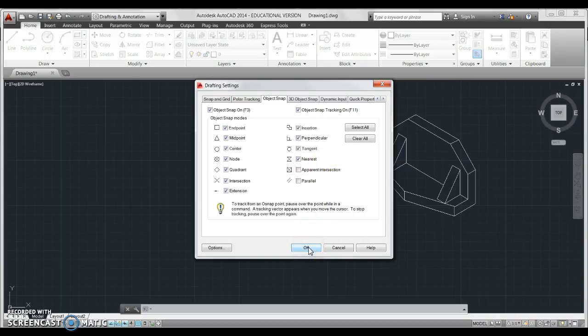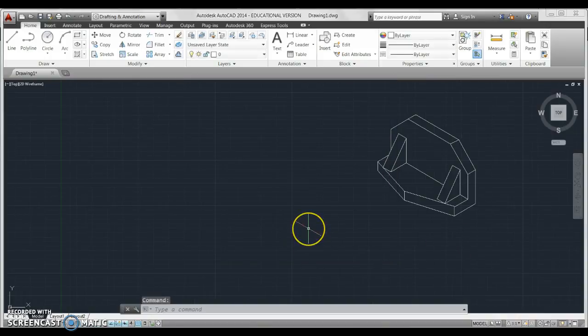And you're going to notice that right now the grid is little squares. When we click OK, it's going to switch to isometric, so these squares have turned into rectangles. And notice my cursor now has a green line and a red line on the axis planes. To toggle the axis planes, we can press F5 on our keyboard.